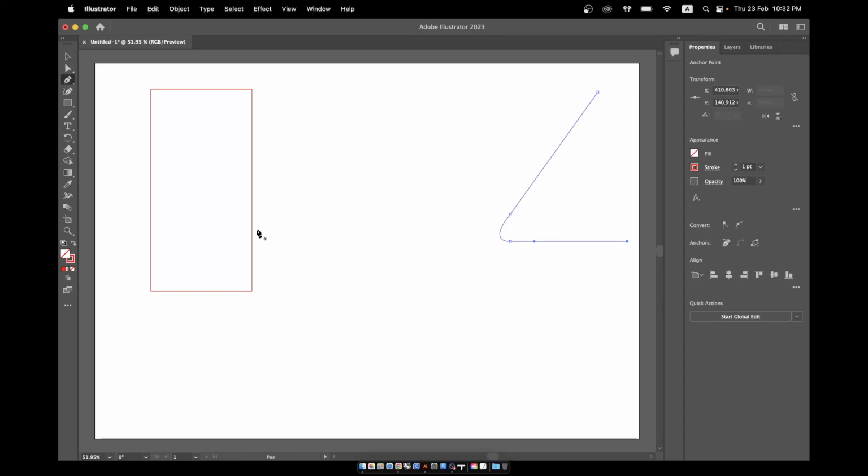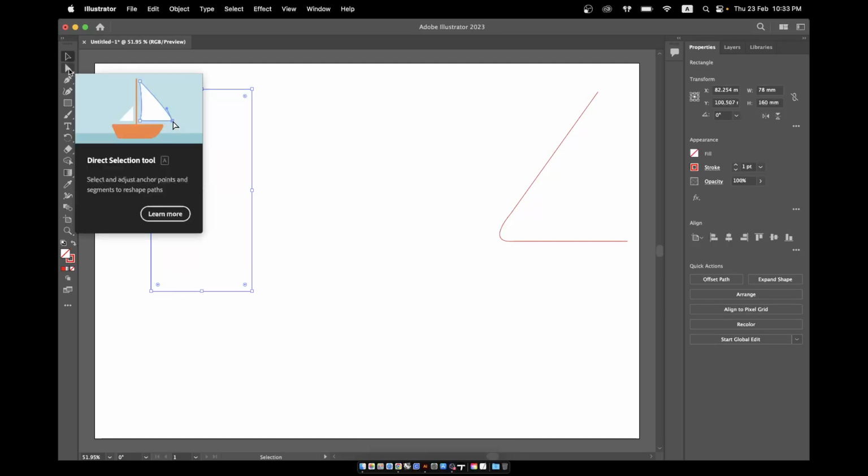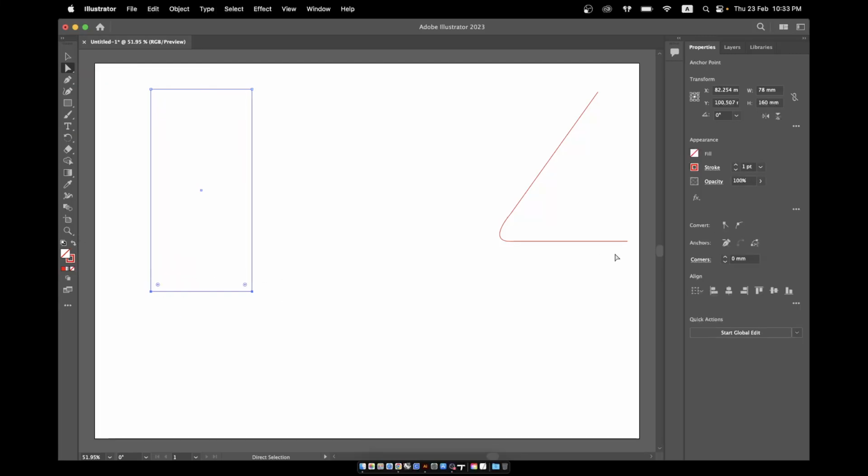So right now what you draft here, the mobile phone size will be somewhere on the top part here. That is the mobile phone. And you need extra pieces here to allow the mobile phone to rest on top of it. So we're going to increase this part using the direct selection tool. We're going to move it downward for 40 mm, so that will make the total height to be 200. So let's go 200, and enter, finish.